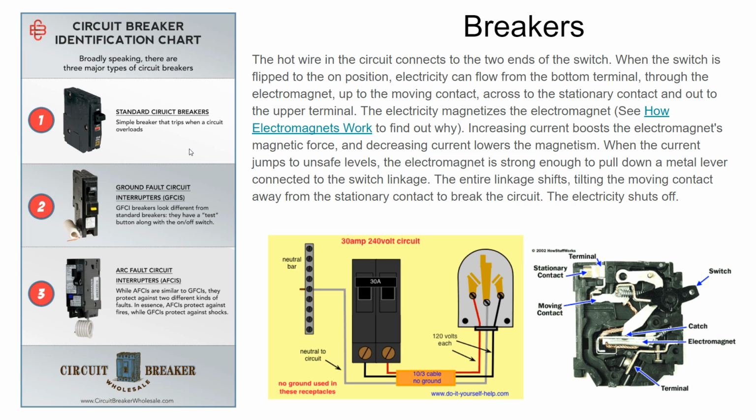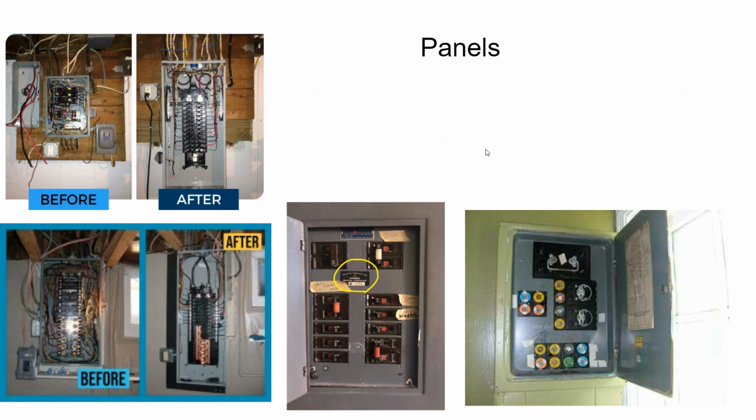I'll tell you, I believe it's the arc fault. I've seen them put in. The electrician I was talking to said that they are so sensitive, if you're putting in an arc fault, if you have the breaker in but everything else turned off, they'll actually trip if you disturb the wire too much. They're that sensitive, which can be a pain in the neck in some ways, but you know that you're protected with other things. So panels, this is what they look like in real life.